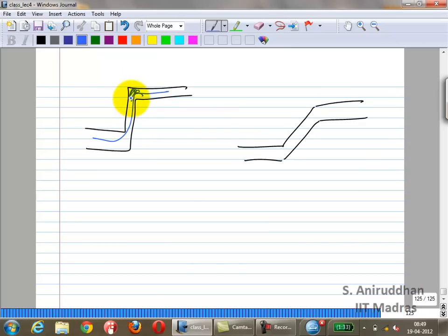What will typically happen is, it won't make a big difference, at least for analog circuits, over the short term, but over the long term, you would have the metal getting redeposited. Okay, that's called electromigration. You prefer not to make very sharp corners. This would typically be much better, the one on the right side, than the one on the left side.